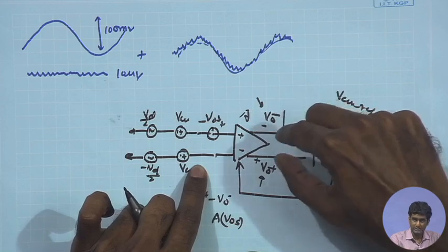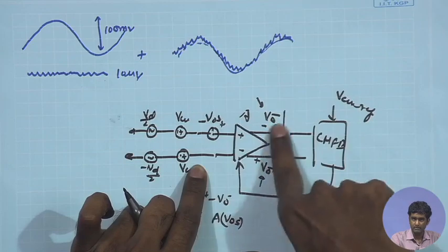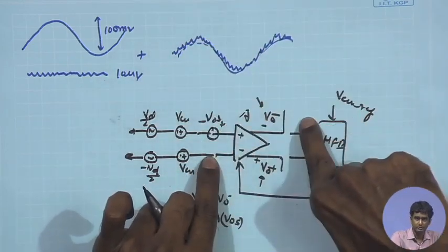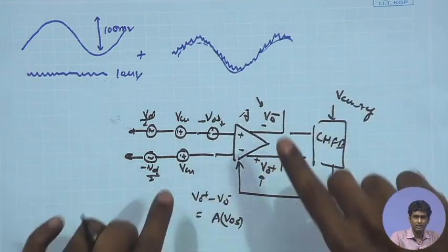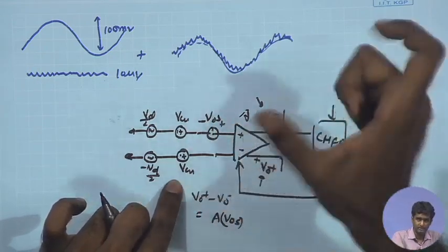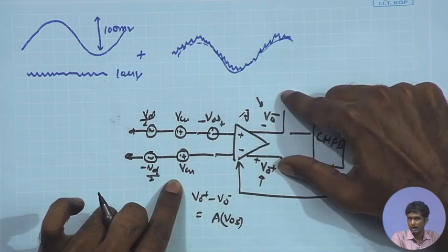So in case we go for the normal operation, suppose that we have a resistive feedback and then we are forcing the output common mode to be having some value. A mismatch over here can, suppose you are having a different bias for the input, independent bias of the input with respect to the output. Under that condition, any mismatch in the input side or the mismatch in the devices in the differential amplifier side, it can create a significant mismatch in the output levels.